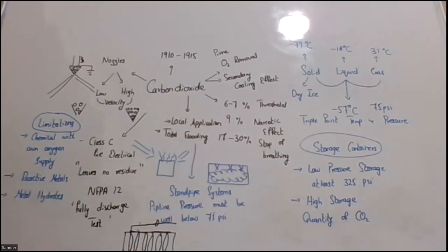available within the environment. Some combustibles may be ordinary combustibles, okay, and they may not require that much concentration of carbon dioxide. They may merely require only a removal of oxygen, okay, to extinguish and cool down. So it may require a holding time of less than 5 minutes, okay. 2 to 3 minutes of holding time is sometimes enough.